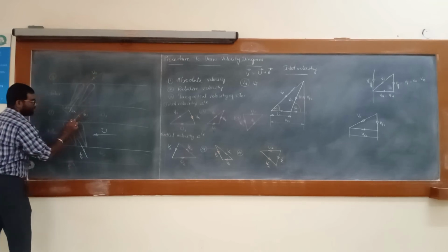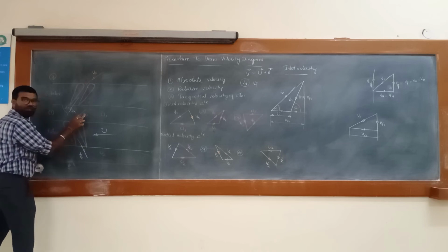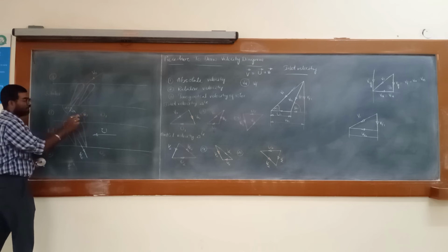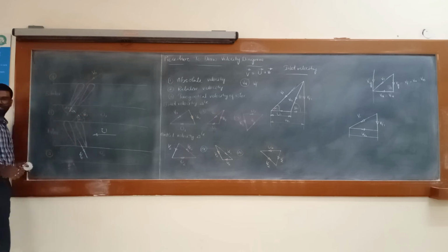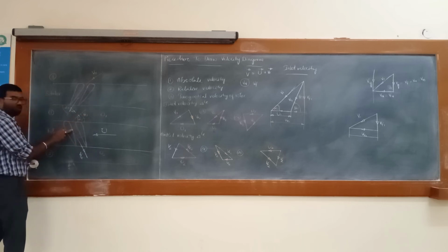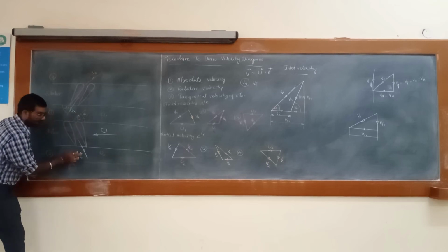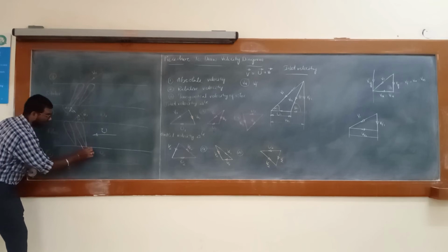Understood? Okay. So here VR1, the fluid velocity, the angle made by the fluid velocity entering the rotor, this is beta 1. This is known as the rotor angle at the inlet, the rotor tip angle at the inlet of the rotor. Similarly here we have the angle made by the relative velocity when it leaves the rotor. What is this?